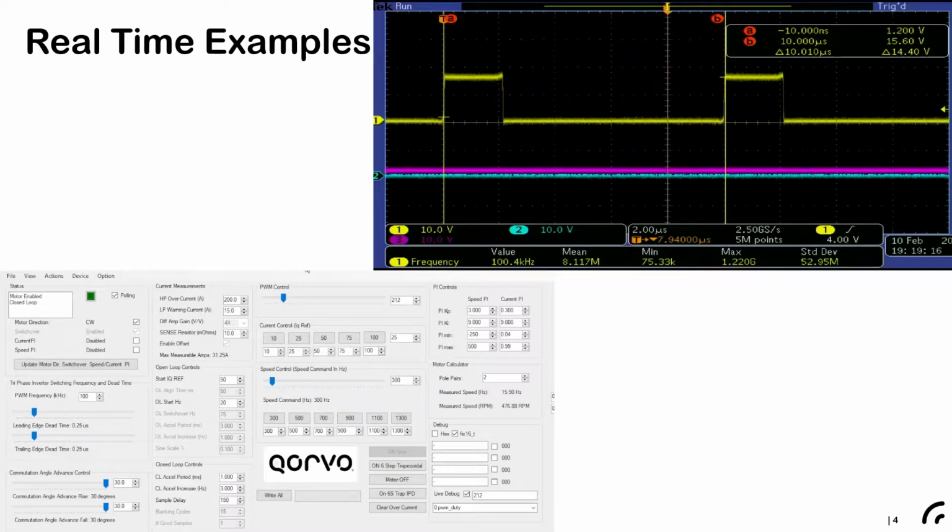But before I go into PWM, let me show you the basics. First thing we talked about was the period. And when you change the period, you're changing the frequency. If you look at the scope, you're going to notice that our frequency right now is 100. That's the default in the firmware, 100 kilohertz. But you can change it here. And when you change the frequency, what you're changing is the period, if you remember from the previous video.